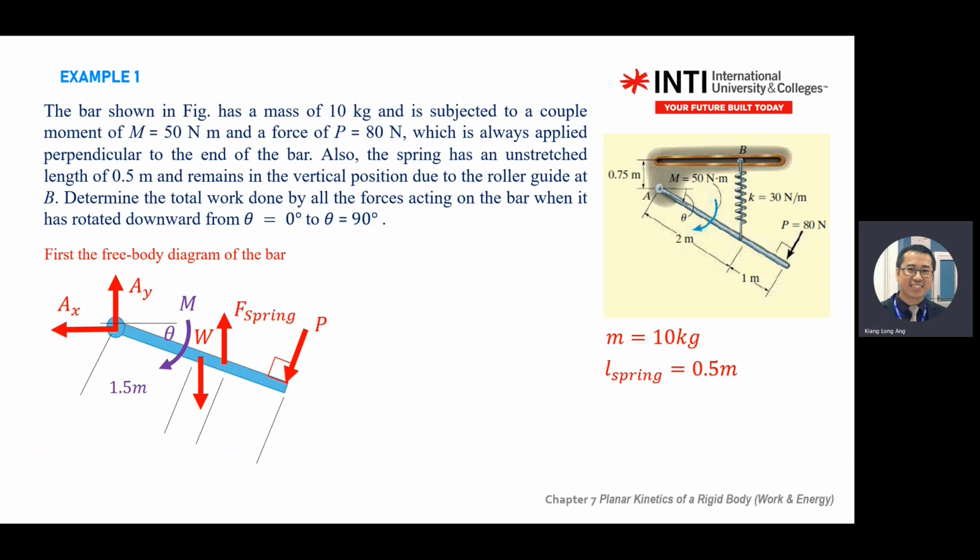So the distance between this slot and this pin, when it's 90 degree, the length here is 0.75. But your spring original is 0.5. So you're going to stretch already. Can you see? When you mount this spring at 0 degree, your length already reached 0.75. So you need to stretch your spring to mount it. That's why before, you already stretch 0.25. This example is stretch.